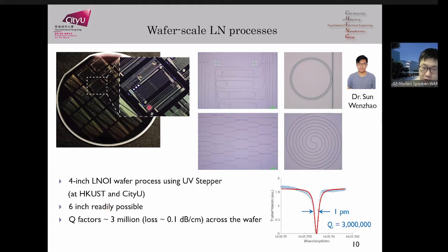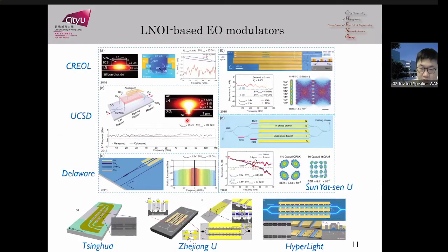And you can build all kinds of devices on the wafer with a low loss of less than 0.1 dB per centimeter. So this work was mostly led by my former postdoc, Song Zhao. And not just us, right? There's an entire community pursuing these thin film lithium niobate devices, and here is just a glimpse of the modulators built by different groups, including some of the more advanced capacitive loaded modulator designs.